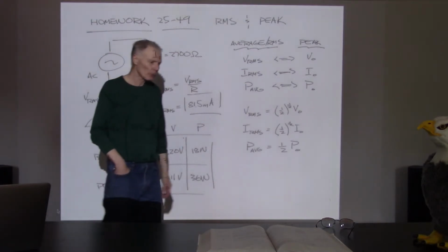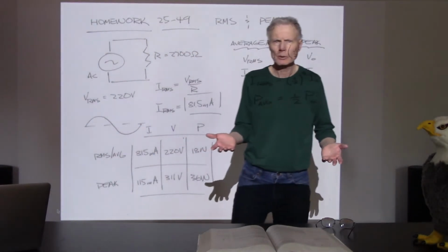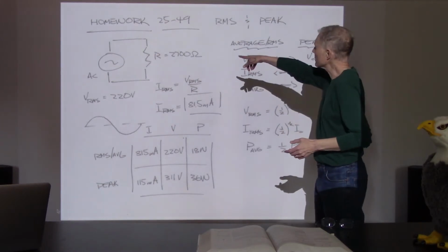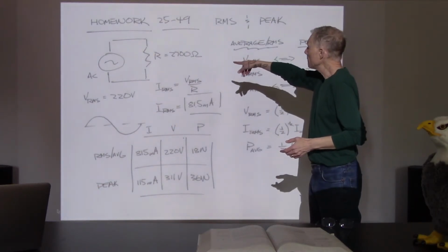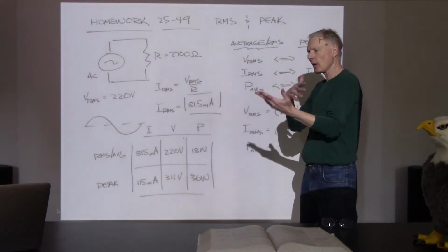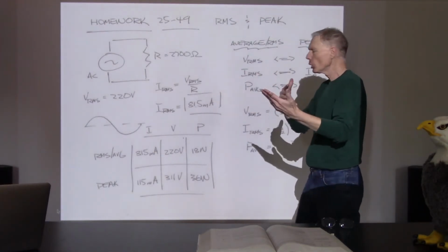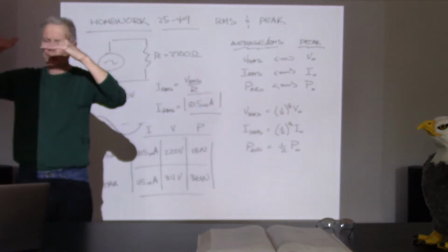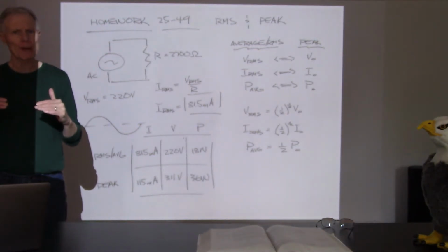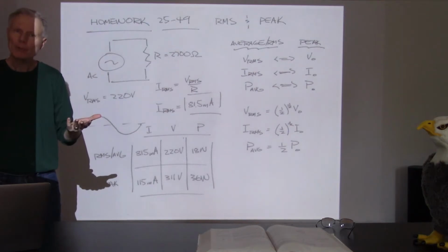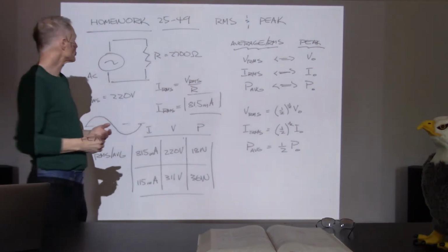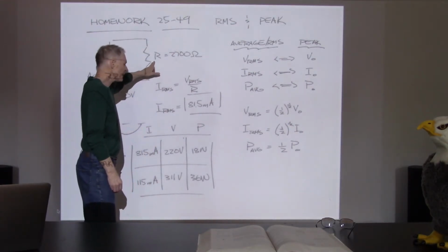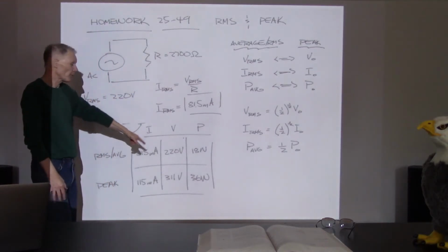So what's happening in terms of power? Power doesn't go negative. If all I have in a circuit is a resistor and the current's oscillating back and forth, when the current rises, the power goes up, but when the current drops, the power goes back down. If the current reverses direction, which it does in alternating current, it really doesn't make any difference in terms of the power.